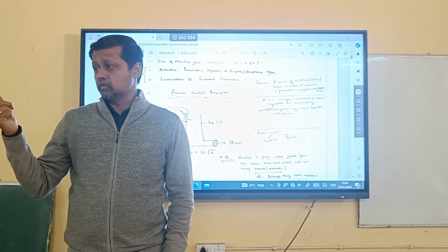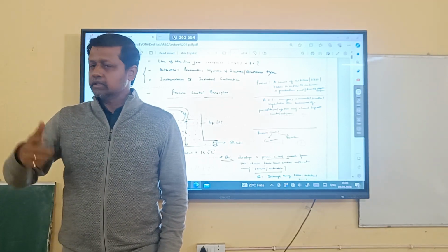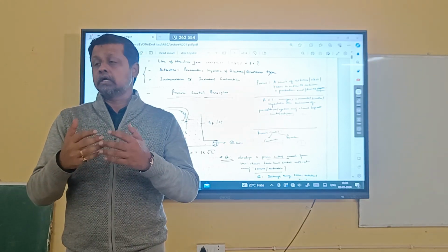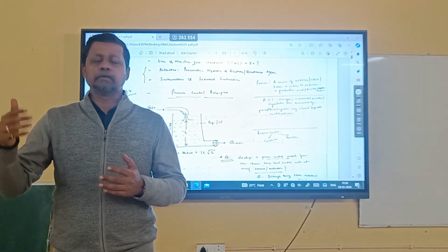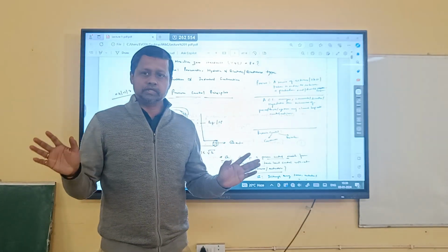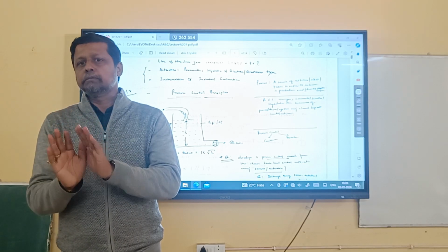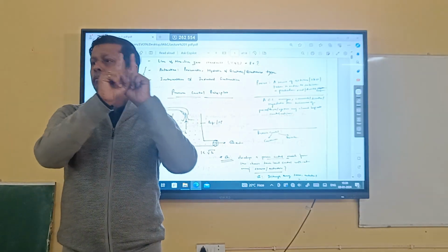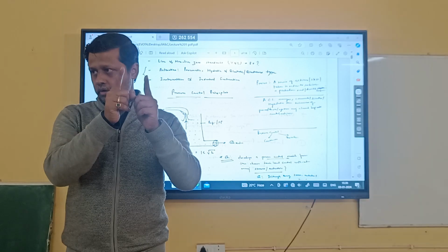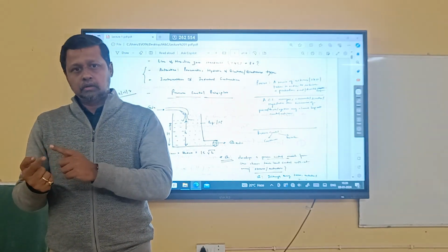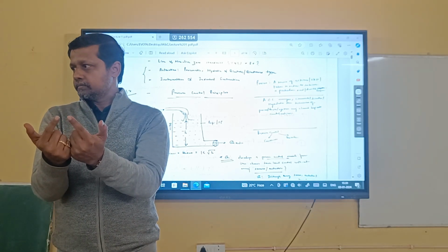So there, the system engineer has opened the controller, reset the algorithms, taken the necessary steps. If needed, he has to add certain additional algorithms also, if the thing was not fully ready. If it is fully ready, then you have to preset certain parameters, reset certain parameters. Once it is fixed, now the system engineer can move from edit mode to run mode, because industry will run in run mode. Automation by default runs in run mode. You have to take it to manual mode to edit it, understand? Now you have to reburn those algorithms or not?